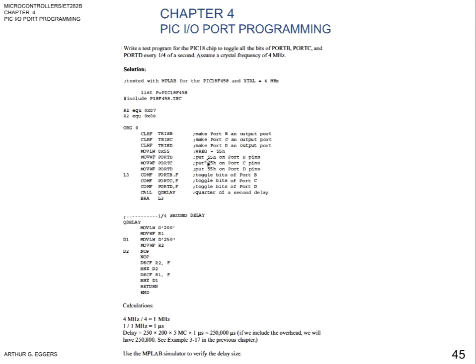Okay, the idea here is that we want to check in the watch window that each of these steps does exactly what it is supposed to, and that you can see it as it's progressing, and you'll have to use the step in function within MPLAB to do that.